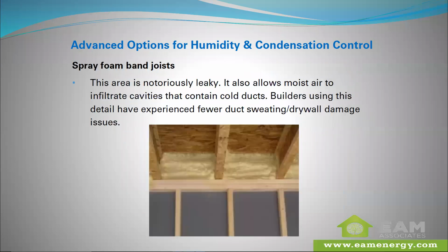Just highly problematic. Spray foaming band joists. This area is notoriously leaky, and it's allowing moist air into the cavities where these cold ducts are located. So exactly where we don't want it to go. We've had builders who were building basically the exact same buildings, in some cases designed by the same architects and engineers, same equipment, and they experienced fewer or no duct sweating issues, even with uninsulated ducts, because the one major spec difference I could point to was that they had closed cell spray foam on their band joists. That was really the only major difference. So that can be an effective solution in helping to cut this down as well.